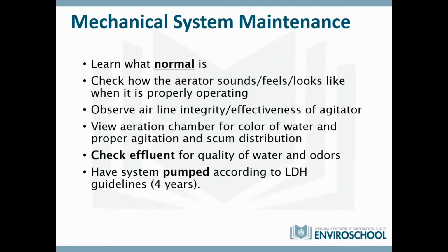So let's go deeper into mechanical systems. These are, again, the aerated treatment units, and some more about their maintenance. This first one goes for all of them, but it's really for these mechanical systems. Learn what normal is. If your system has just been put in, or it's just been maintained or cleaned out, go look at it. See what it smells like, what it looks like. Touch the blower pump, see how it feels. Maybe touch the cover on the outside of it. See what that feels like, because any change of any of that could indicate something's going wrong.